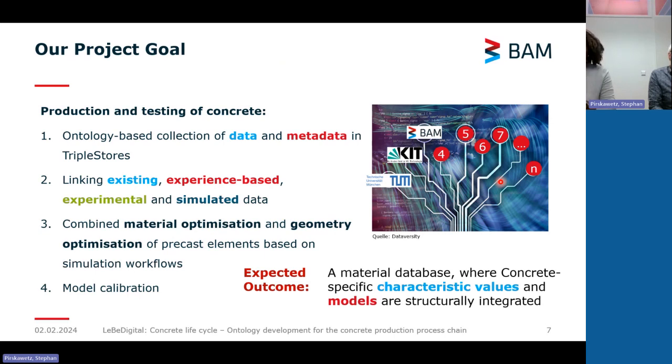We also aim to combine both the material composition and the geometry optimization of precast elements based on simulation workflow. And also we want to do model calibrations. So overall, what we aim is to have a material database where concrete-specific characteristic values and models are structurally integrated.